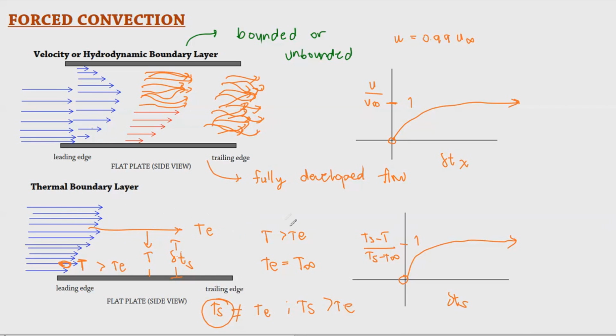That's a different story when the temperature of the surface is lower than the temperature of the fluid inside. Then the temperature in the thermal boundary layer would be less than the temperature of the uniform or free stream, since the temperature here is a lot lesser. But anyway, in cases where we have fluid and a temperature gradient, we should know that convection will happen.